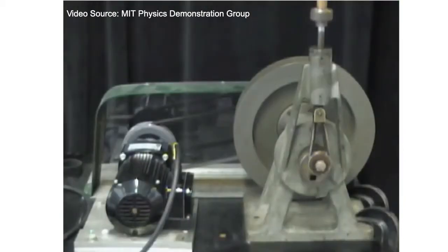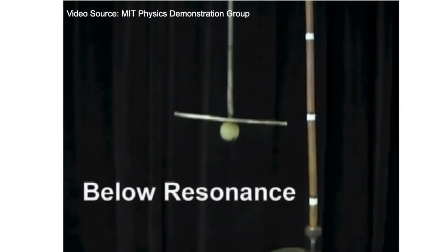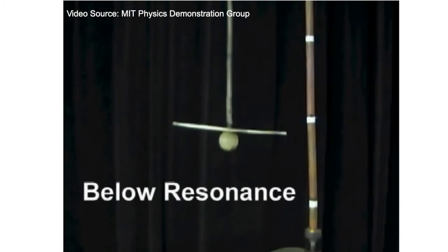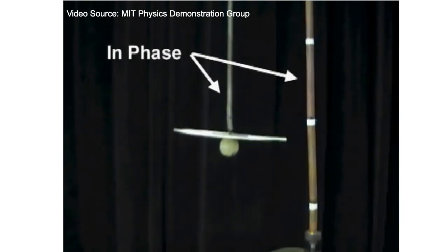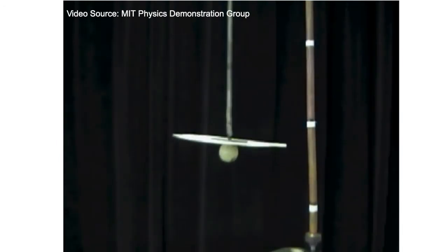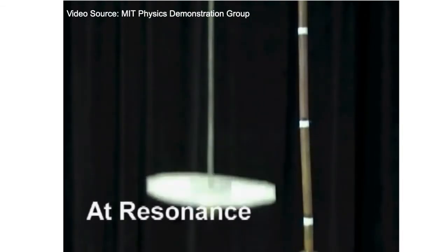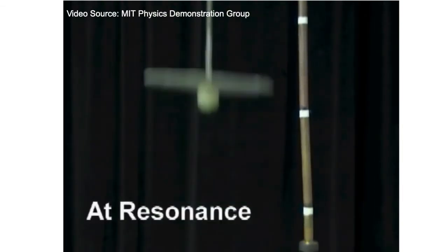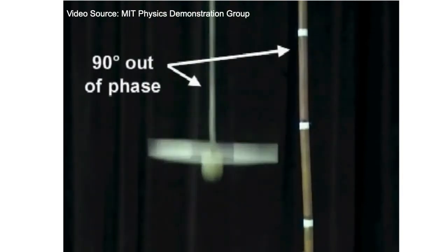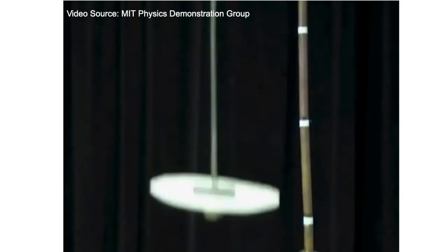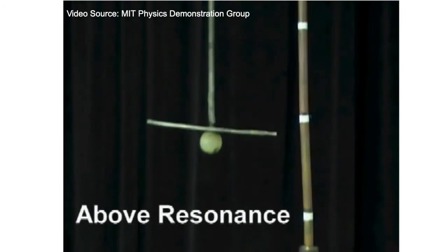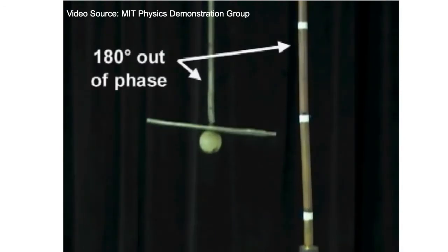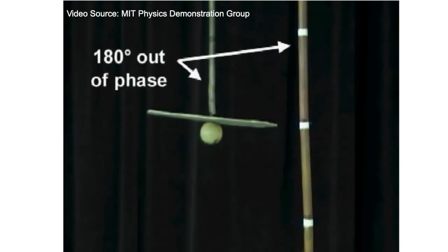The single degree of freedom is formed by a mass attached to a spring, and you can assume very little damping. If the frequency of the action is lower than the mass spring system's frequency, we are below resonance, and the motion is in phase with the force in action. At resonance, the displacement is massively amplified and the response is out of phase with the action by 90 degrees. Above resonance, the displacements are low and 180 degrees out of phase with the force in action. As the tuning ratio increases, these displacements will tend to zero.